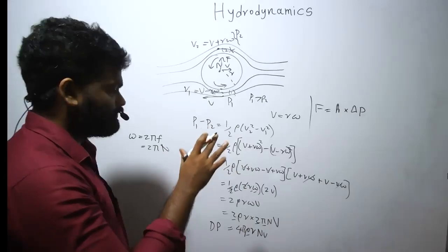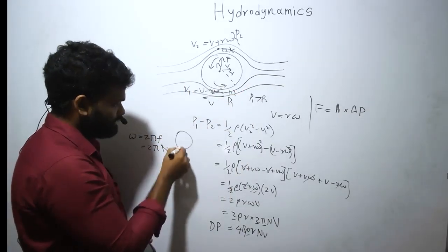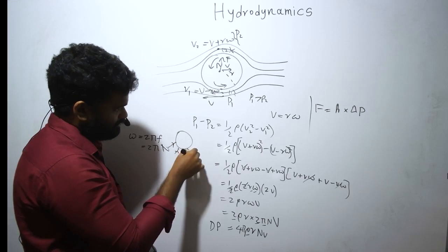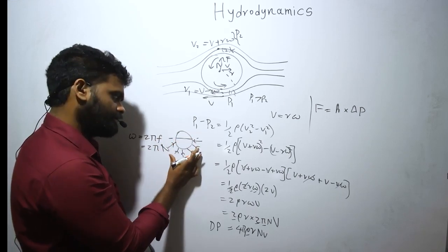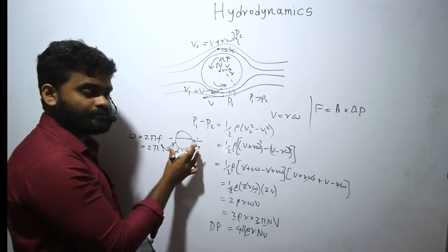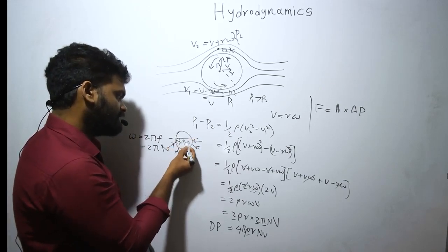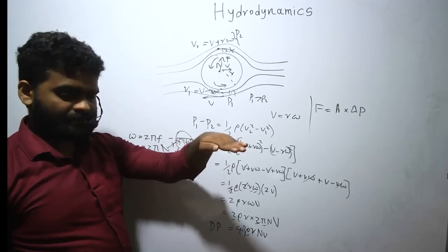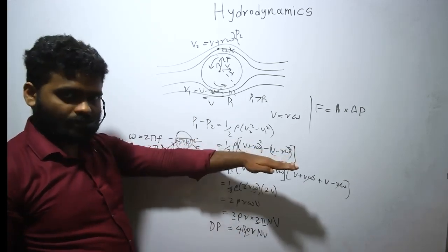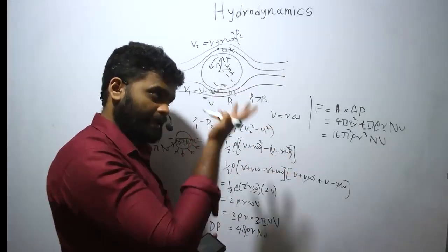So you can see when you take the ball and the pressure forces are applied like this, if you take the resultant pressure forces, you can consider that pressure forces are applied like this on this area. So that area is a circle, right? When you cut the ball in half, the pressure forces are applied on that area.